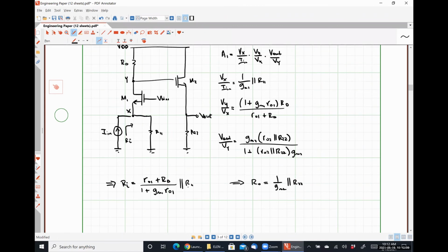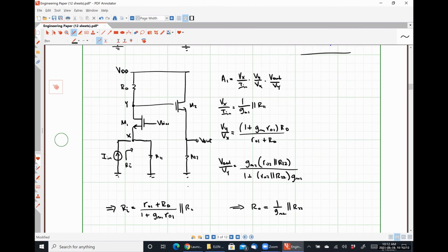Now, just to be clear here, our open loop gain is positive, this is positive, this is positive. So this winds up being a positive feedback system because our feedback factor has a negative value. But the analysis method that we're using is still perfectly valid to analyze this. I apologize for bringing the wrong example problem worked out to class. I guess the other one's sitting on my desk, but everything that we did in here is still applicable. So that is enough out of me for today, and for this whole class, unless you've got something else you want me to talk about.